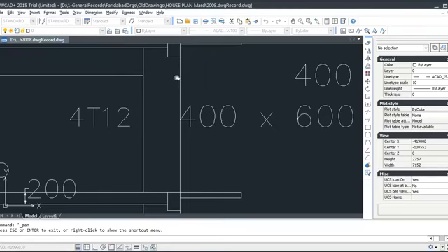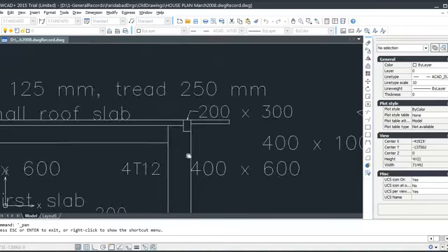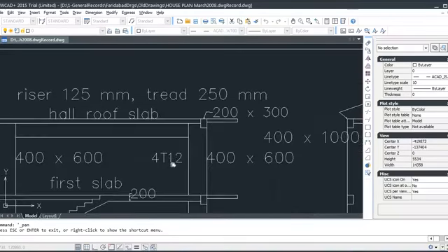We don't take 4 times, or we use shutter here, full height shutter of column. That is real technology. Means we have good 18 mm ply, and you have 2 into 3 inches or 75 into 50 mm or more, and then you have tie bolts in this, and ties and clamps like that, and then supports. I have shown all these details in separate talks. I think if you have seen that, fine. Otherwise, I'm just telling you.